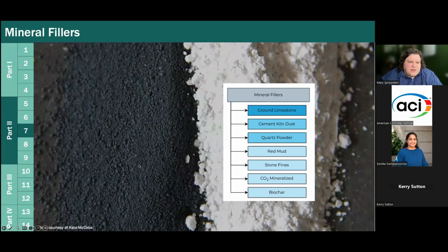So in the picture here, on the left is silica fume, and on the right is silica flour. They're both made of silica and oxygen. They're both fine materials, although silica fume is super, super fine. It doesn't look like it, but it really is. But these are totally different. Silica fume is super, super reactive. Silica flour is largely inert.